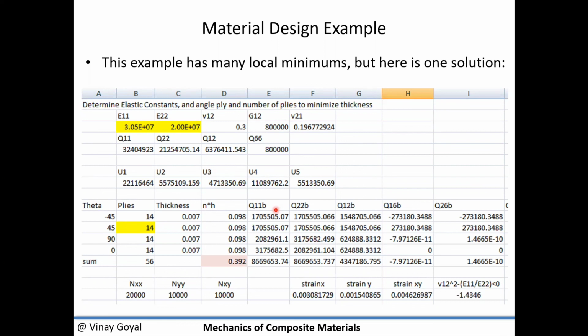There are a lot of codes now that can give you that information, but I think there's a lot of value in you playing around with this stuff so you can build an intuition. For example, if I have a loading condition of 10,000 pounds in one direction, but a very limited amount of load in the other transverse direction, you should be able to come up with a ply stacking sequence that makes sense and will take that load. And if I add shear, you may want to develop the intuition where you don't need to be using optimization codes all the time. But in the meanwhile, there is a lot of value in playing around with these codes and trying to understand what the codes are trying to do, which I think is a benefit of this particular lecture.